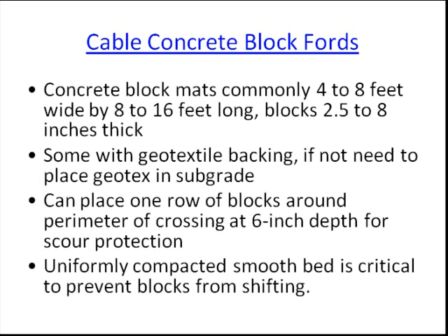Some come with a geotextile backing already attached, but if not, a layer of geotextile should be placed on the prepared subgrade before the blocks are placed. Scour protection around the mat area is important, and this can be accomplished by placing a single row of blocks at least 6 inches below the finished subgrade around the perimeter of the mat.